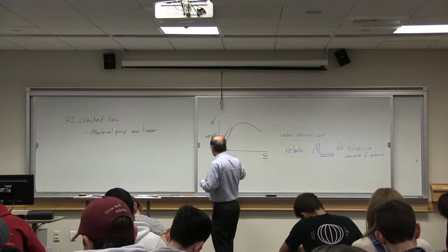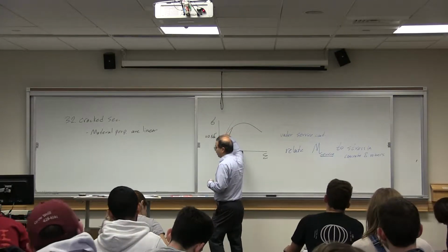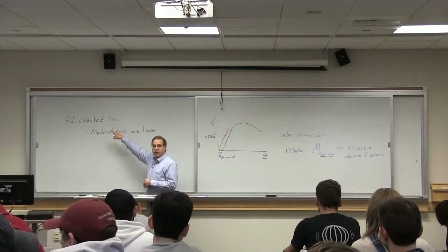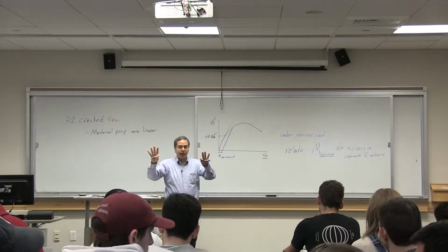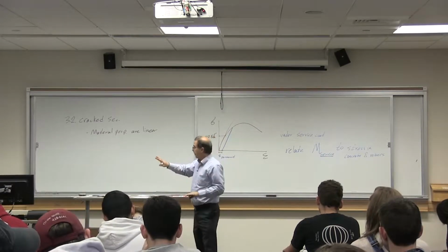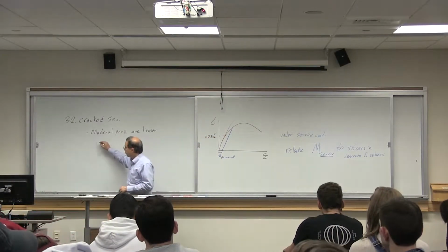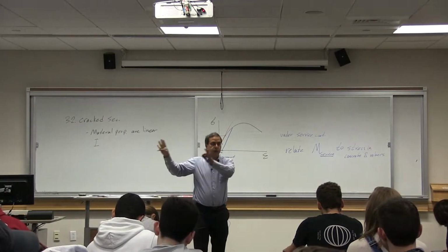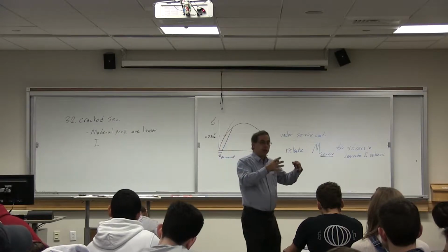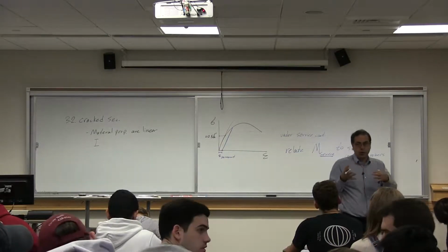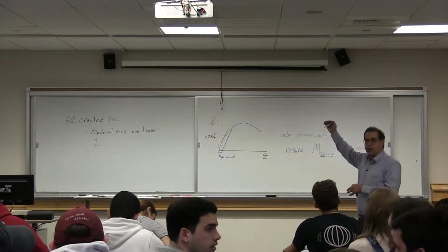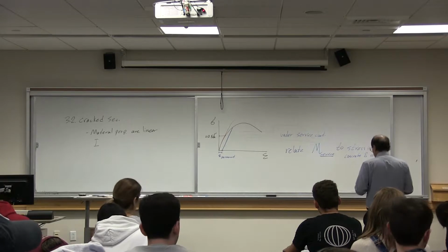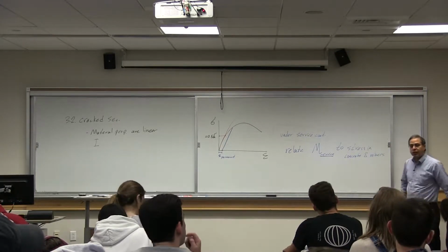M service, that means again limiting the stress below some level, as well as maintaining linear properties to be able to apply this method. There are two things in parallel, almost independent. One, if you want to use I, your material properties need to be linear. That's one domain. Another domain is if you don't want to impose damage to concrete in compression, don't go beyond the linear limit. So they go together, and as a result, this is what we are talking about. Any questions so far?